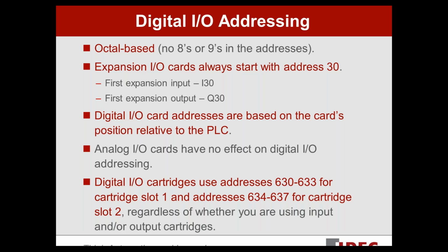Now, analog I/O cards, they have absolutely zero effect on digital I/O addressing. Okay? In other words, I can drop analog cards in there wherever I want. Doesn't matter. They have no effect on the addresses of the digital cards.